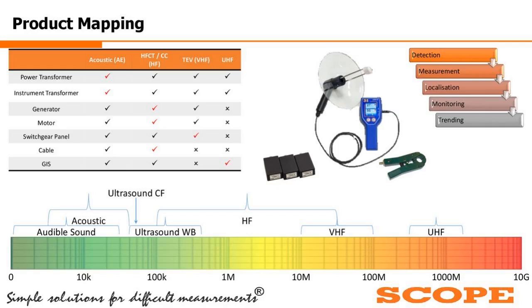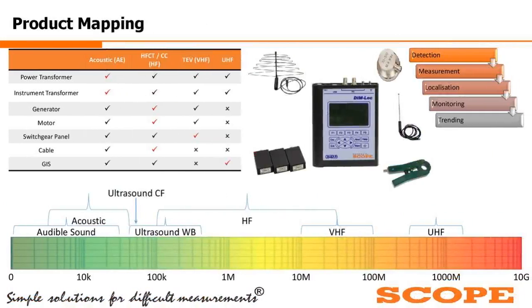Second, you have got this particular solution, a handheld product that has all the kinds of sensors that we discussed. You have got your ultrasonic dish, as well as the TEV sensor and the coupling capacitor, as well as your HFCT to detect PDs.